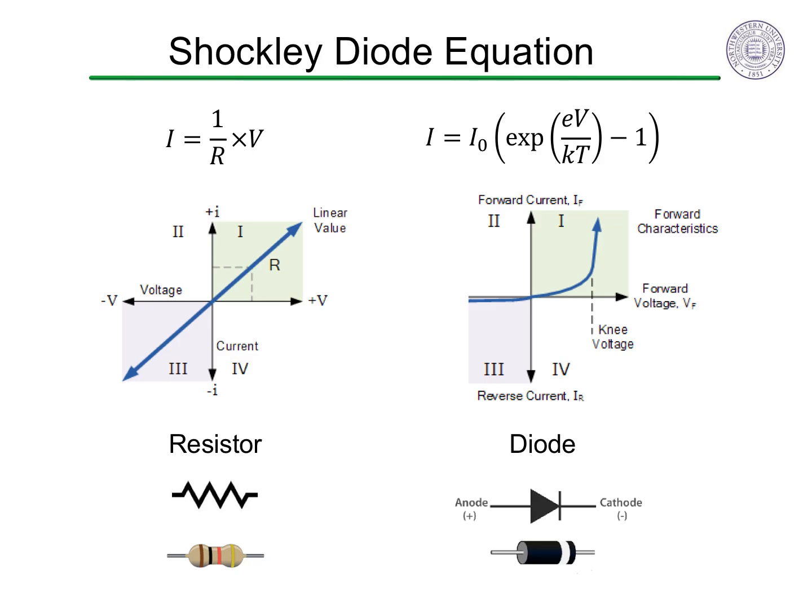The simple PN junction diode is also a passive device that doesn't produce power, or at least not under equilibrium conditions of constant temperature and no illumination. Under zero bias, or V equals 0, the resulting current is 0. However, when a positive voltage is applied, the current increases exponentially. On a linear scale, the current seems insignificant until a particular voltage is reached, and then it rises rapidly, like hitting a knee in a curve. We call this forward bias.